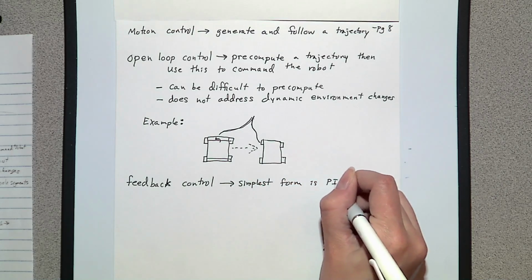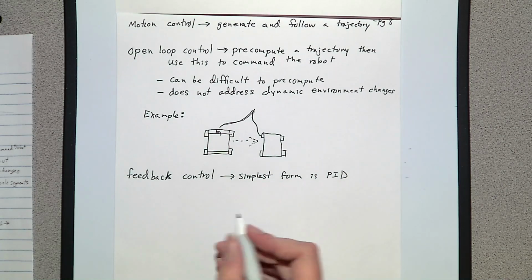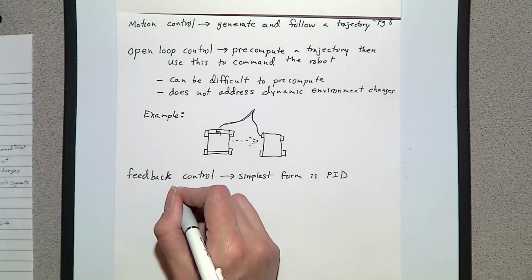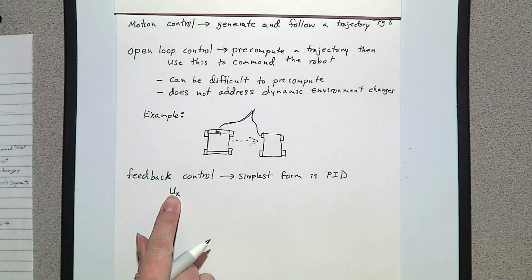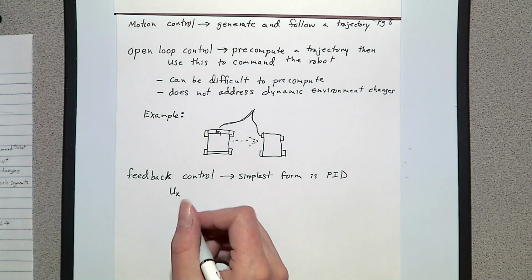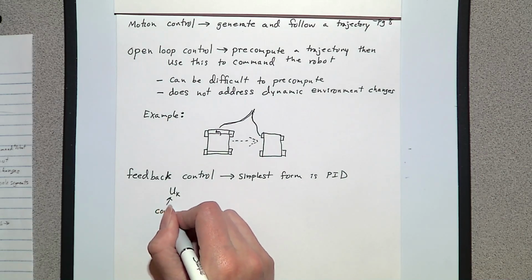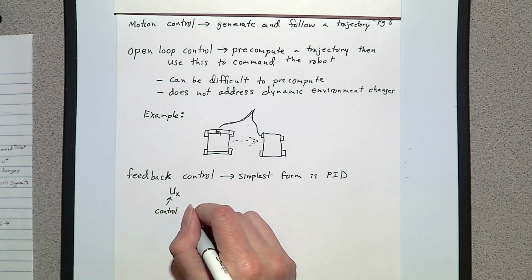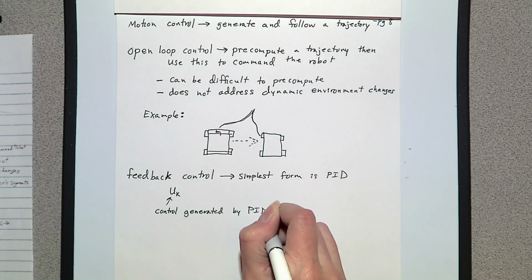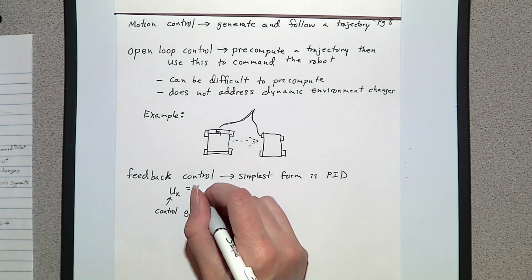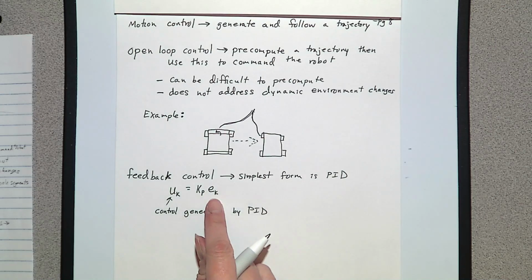which is a PID type. I'll do the definition first. So if this is our control input U out of the PID, we have our proportional gain, which looks at just the error at that time instance.